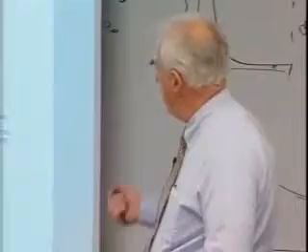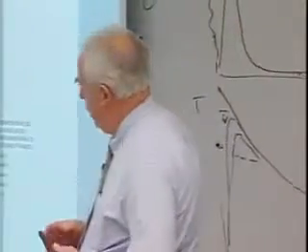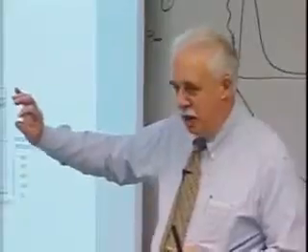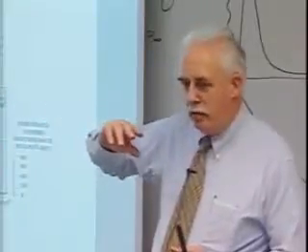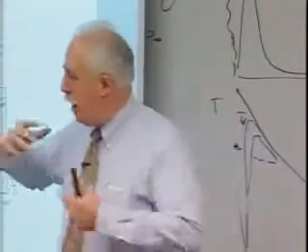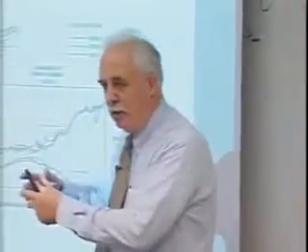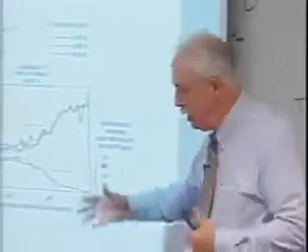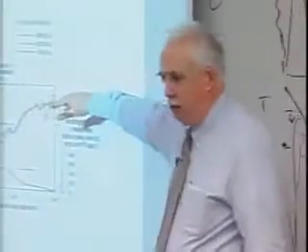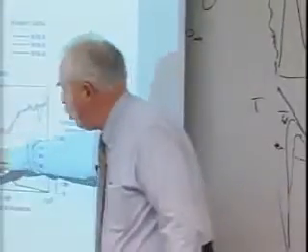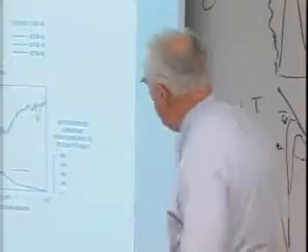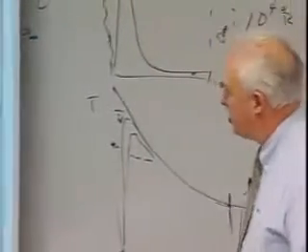There are, in ballistic facilities, if you have a particle traveling, or a vehicle traveling at high speed, eventually your wake goes transitional and turbulent. As you increase the Reynolds number, that moves forward. As that moves forward, you get more mixing. As you get more mixing, the gas in the wake gets hotter, and I believe that's fundamentally what's going on, and it's very repeatable. Okay. We cannot get this in the wind tunnel. Okay? Okay, now we'll go to TPS.